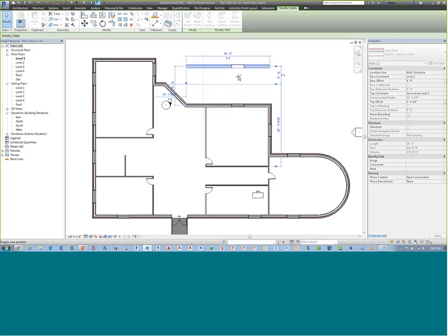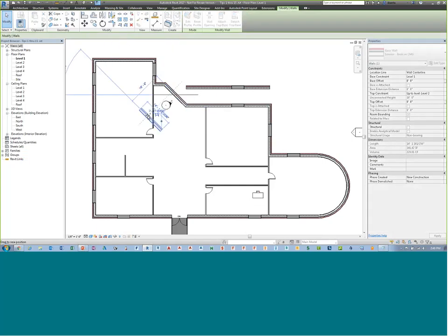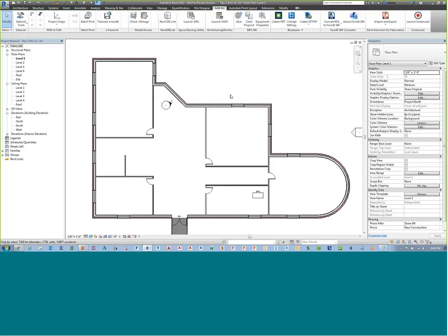If you try to move your mouse at an angle, it won't do that. It keeps it aligned to that entity. Now, if I do the same thing on this angled wall, it keeps it aligned to that angled wall. See that? That's kind of neat. You can use the shift key in combination with your control clicking to create additional content.